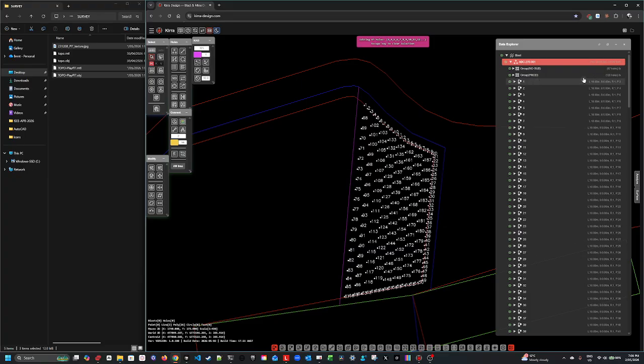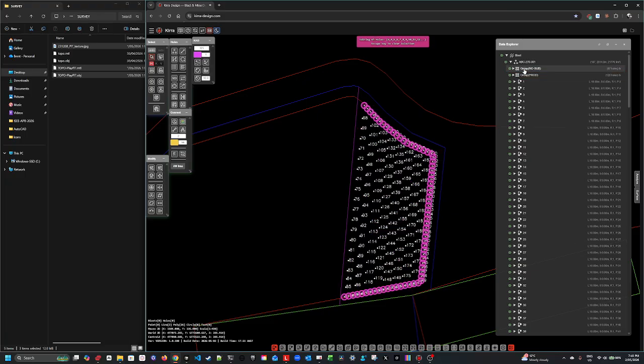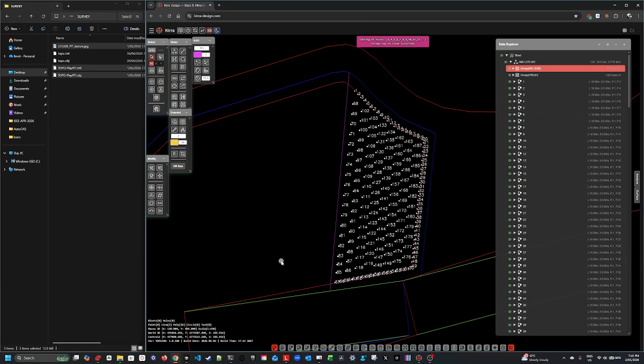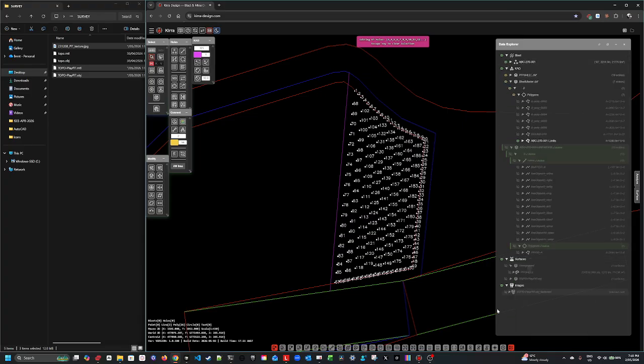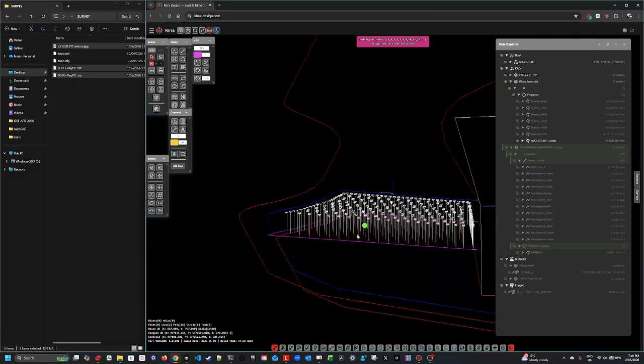Okay, so we've got 120 holes and 67, and that adds up to a total of 187. So that's good. If we grab that, there are all our production holes. We grab that, that's all our buffer holes, or sub. Okay, good work. So everything's good. What haven't we done? Well, we need to assign these holes targets, because they're just in midair at the moment at default elevations.